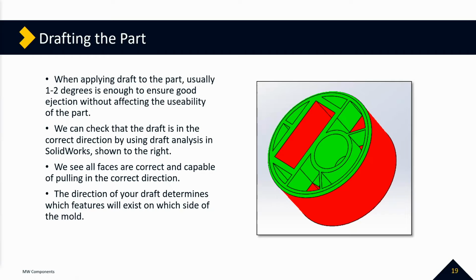On the right, that's just draft analysis in SolidWorks, just to show that this is drafted by about 1 or 2 degrees on either side. We see that all the faces are correct and capable of pulling in the correct direction based on this draft analysis.